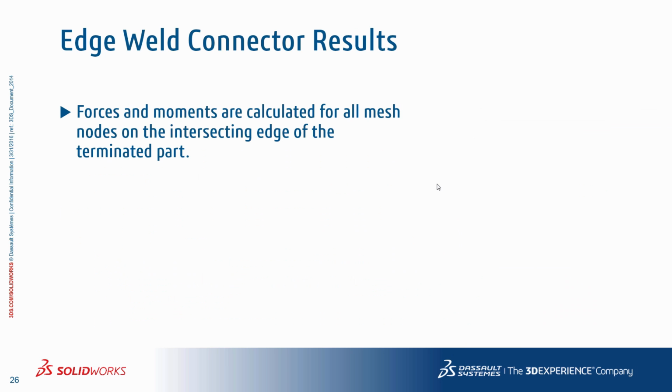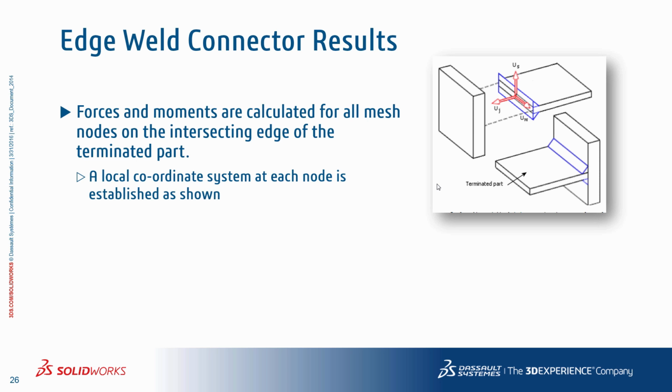So again, the forces and the moments are calculated for all the mesh nodes on the intersecting edge of the terminated part. So behind the scenes, a local coordinate system is created at each and every node as shown.